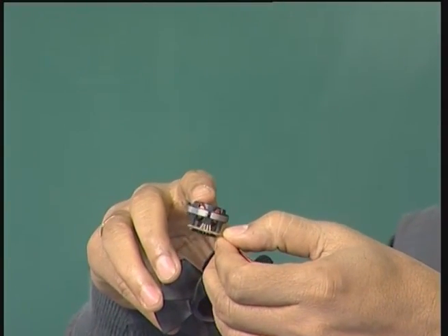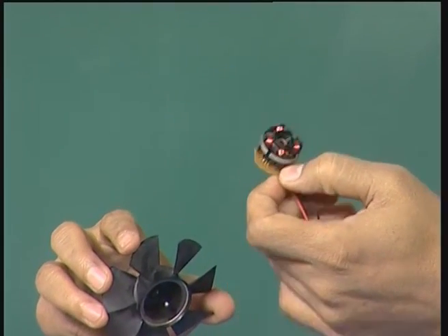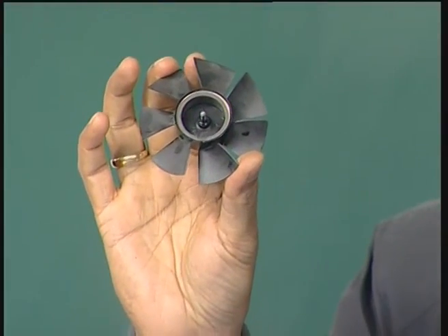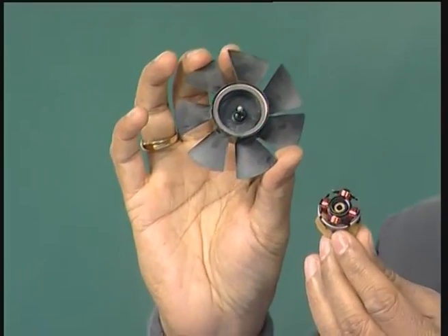When the windings are switched here, the field is produced in the stator, and when the field is produced in the stator, there is a torque production, and as the rotor rotates, the field goes on shifting, and hence there is a continuous rotation. So, this is a very inexpensive motor, but this is an example of a brushless DC motor. We do not have any brush. You can see here this structure does not have any brush. So, the disadvantages associated with brushes and commutators are done away with. So, this is an example of a low cost brushless DC motor, and in this case the rotor magnet positions are detected using Hall effect sensors.